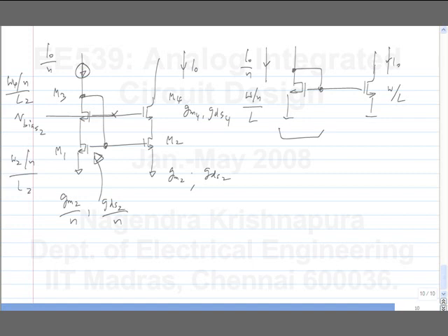And this is very common. The reference branch currents are smaller than the main current. Now, what is the output noise you see here? Let's say this was biased with an ideal voltage source of the appropriate value. What will be the output noise current? M2, M1. What is the output noise current? Yeah, what is it? 8/3 kT GM2.